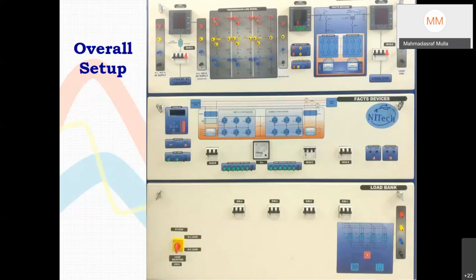So, design and development of VSC-based FACTS controller. In summary, I will say that VSC-based FACTS controllers can provide reactive power from some lagging maximum kVAr to leading maximum kVAr, and you require a very small volume for this circuit because these circuits are designed with high frequency.